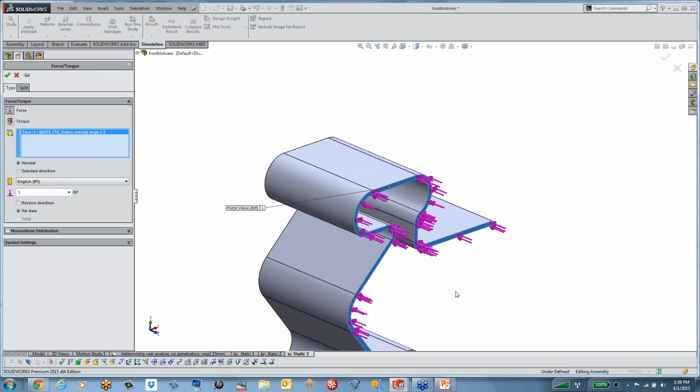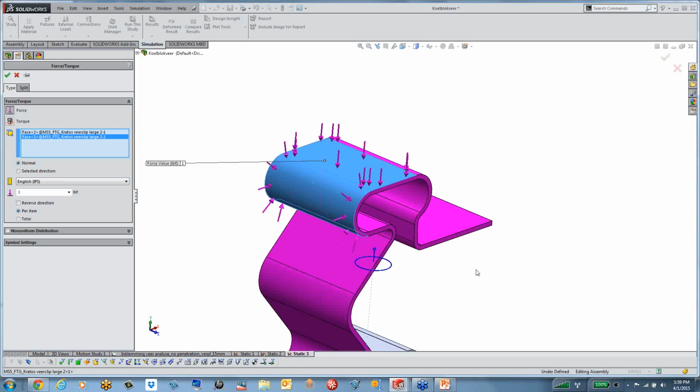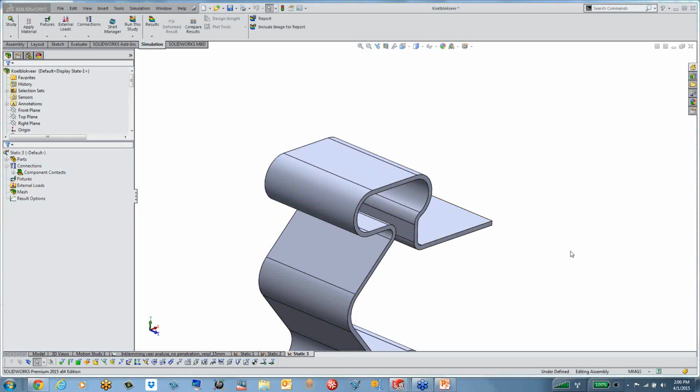So from a geometry perspective, I can simplify this to a 2D scenario, but now when I look at the load, the way this thing is loaded, I cannot do it because it's acting normal to the cross sections. It has to be the load. If the load is somewhere here or here around the cross section area, then yeah, that's the requirement for solving this problem as a 2D analysis or a plane stress problem. Okay, so we can certainly send you some literature or information on when to use 2D analysis and what are the different rules that we need to follow in order to be able to actually use 2D analysis. Well, lots of questions.